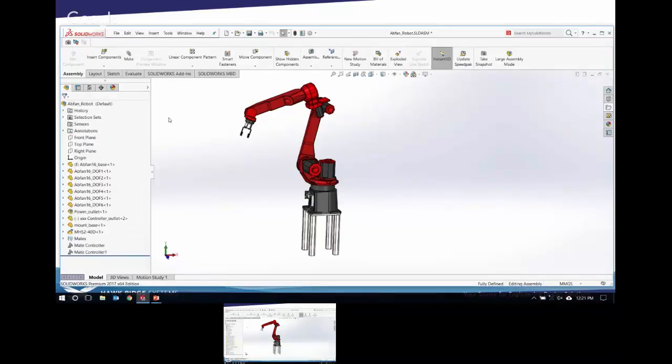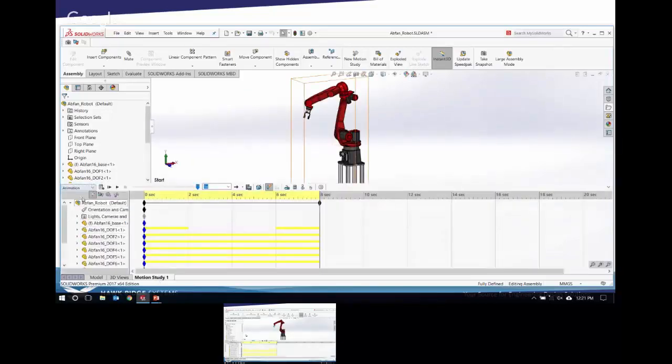One of the things you can do inside of a motion analysis: if you brought that into a motion study, and then you turn on motion analysis, you can check interferences at different frames in the motion study. So, I mean, you could see the point when they started to interfere would be the collision. I think that's probably the closest you could get to that.